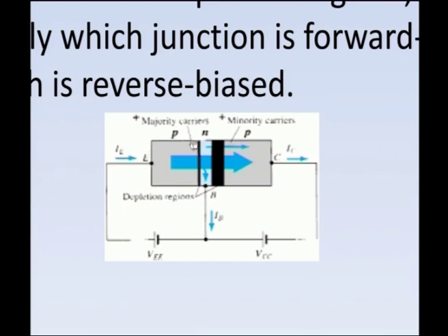We are considering the total transistor part as a node now. So, here this E, this B and this C are all at one point, so that is considered as a node now. IE is the current flowing towards the node, and IB and IC are away from the node. So, IE is equal to IB plus IC, the IB current plus the IC current.